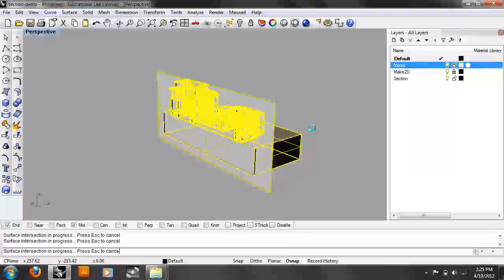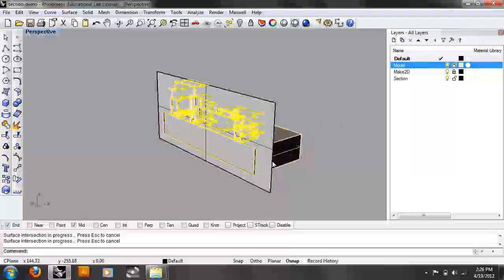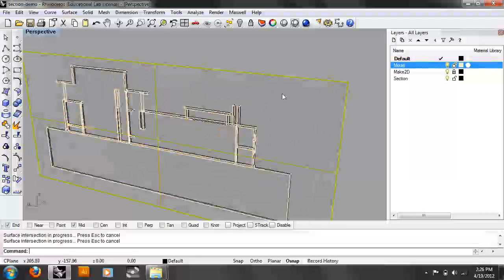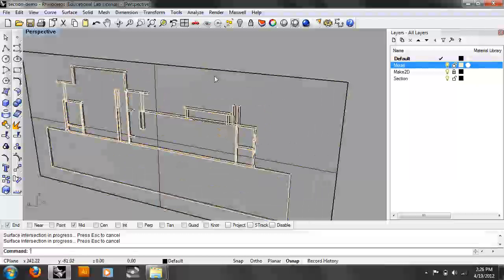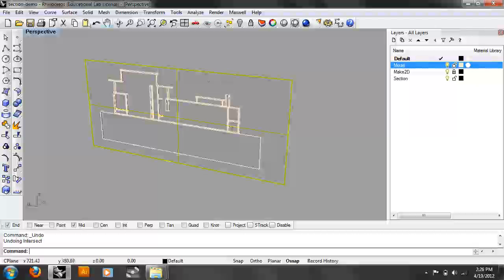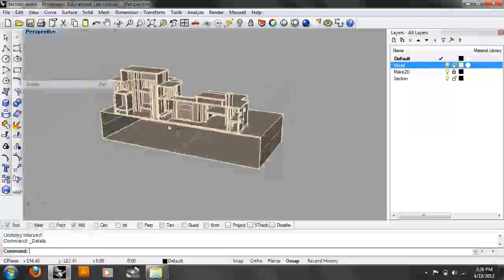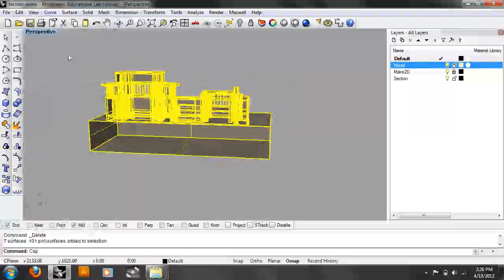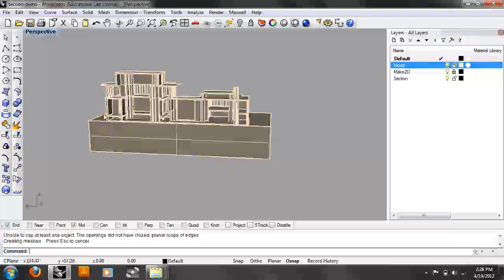So anyway, I think this method actually would work. So you would get all these curves, and then you trim them up, and that wouldn't take you that long, and then just make a surface out of those, and that'll give you one clean surface that you then just move in the X and snap it to the end. Okay. So let's just assume that all that's going to work here. Okay, and I'm going to remove this. Let's go back to Andy's method here. It's easy. Pretty good.